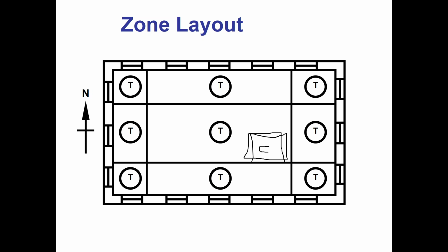right? So for example, I may have a zone that is 1,000 CFM on design day, and I may set it up for 200 CFM minimum airflow to get my ventilation air. So now someone has to go into that controller and say 200 and 1,000 are the mins and maxes, and then the box can modulate in between those two as space temperature demands.